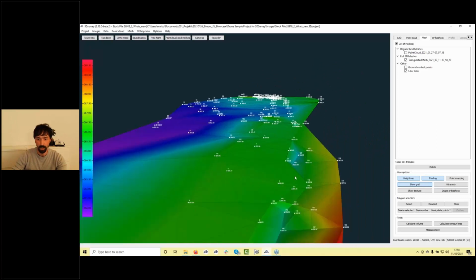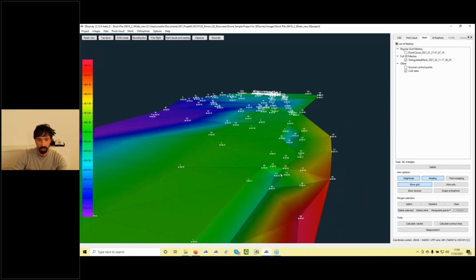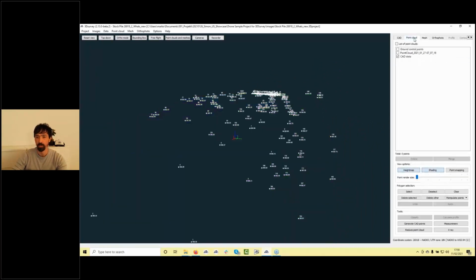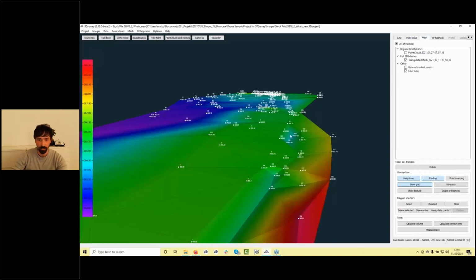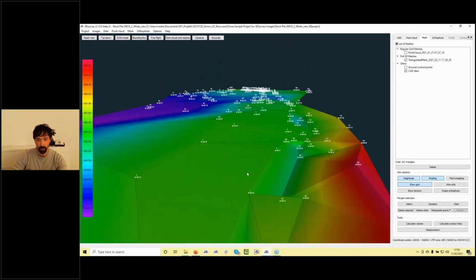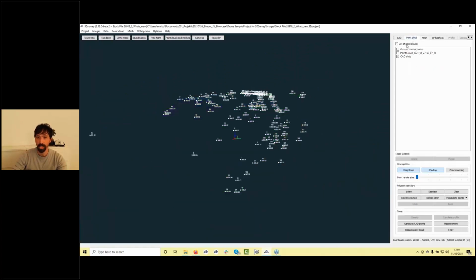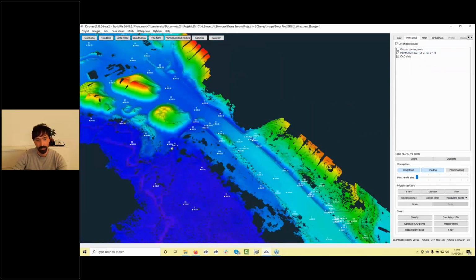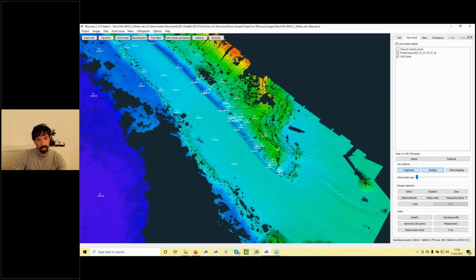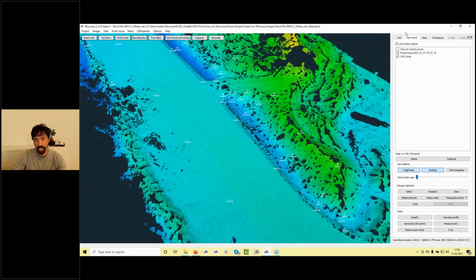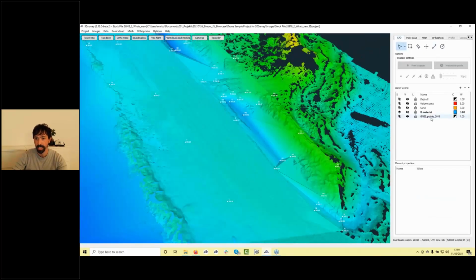Then what I could do in addition, I could create some break lines. So maybe, because I see the mesh was here not perfectly connected, what I could do is go back, turn my point cloud on. This is from the new measurement, but probably in this part nothing changed, and go back to CAD.